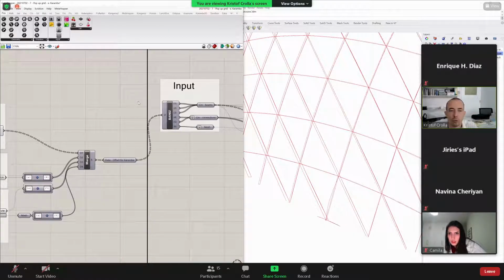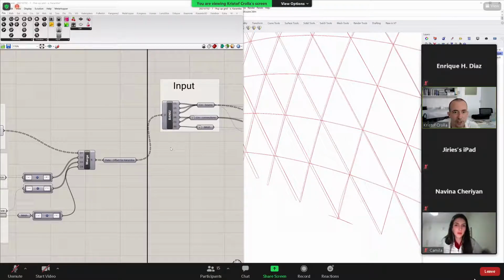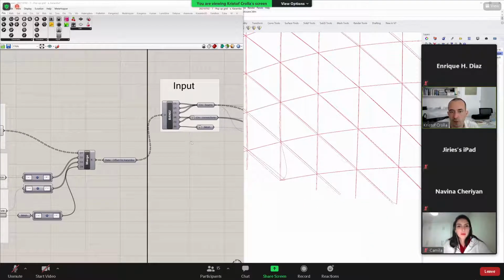You can bake it to different layers, which makes it easy, but you can also bake attributes to your geometries with plugins like Elefront, for example, to give each object an ID, like a name, and embed its data structure in that name. Then you can extract the name again, deconcatenate the text, and reassign it to a particular data structure that you want to have. So this is as close to a fully automated script as you may want to go,